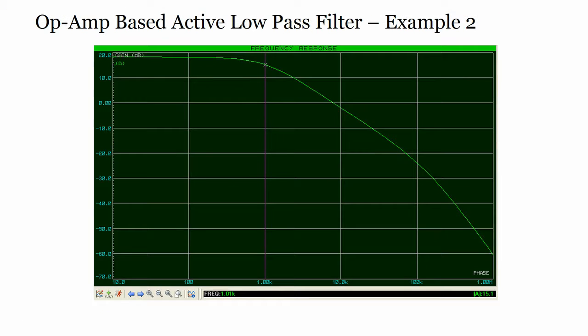and active components. When you actually perform this experiment and you see the signal, you will find this slope here, and like I said, there will be some cutoff frequency somewhere next to here, and you can find this slope nearby the cutoff frequency. You can understand whether this is a single order or single pole active low pass filter. This is the amplitude and this is frequency. So, let us see